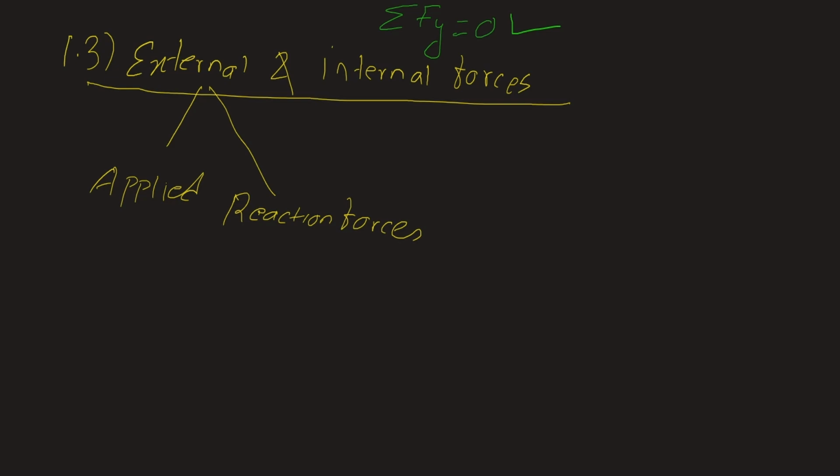Typically, applied forces are the loads that are being applied to the structure under consideration, and they are usually known. And reaction forces are the forces exerted by the supports on the structure and have a tendency to prevent its motion and keep it in equilibrium.